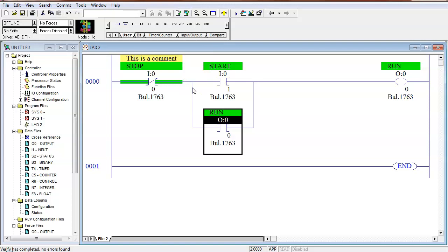Okay. So we've got our PLC in remote, which means we'll be able to switch it between modes. We'll bring it down to program automatically. So right up here, click on the little scroll button and go to download. Yeah, this is the part number for the PLC. So did you select the 1100 PLC?